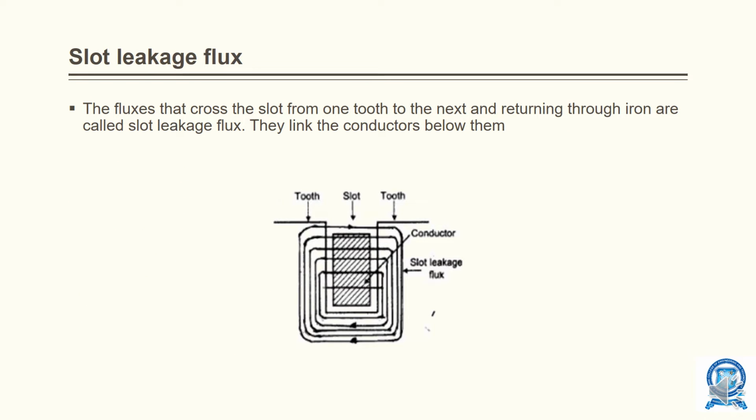First, let us discuss the slot leakage flux. The flux that crosses the slot from one tooth to the next and returns through iron is called slot leakage flux. They link the conductors between them.